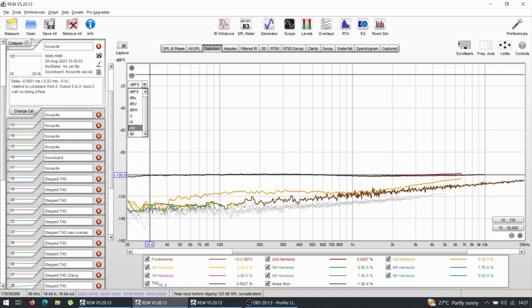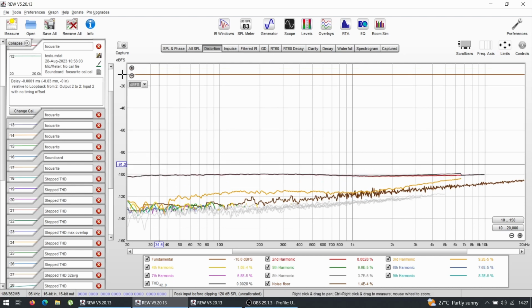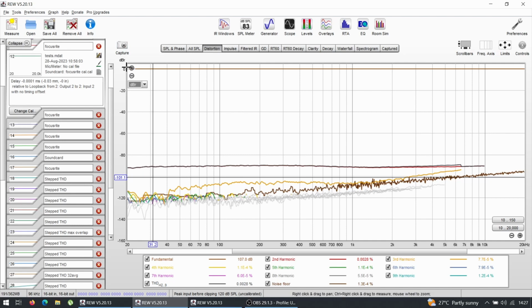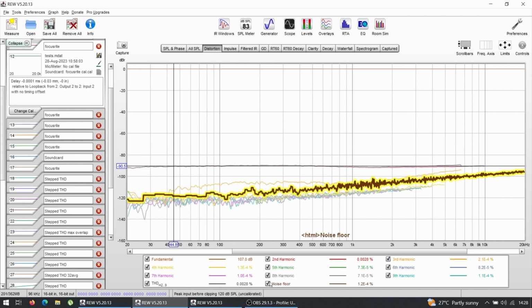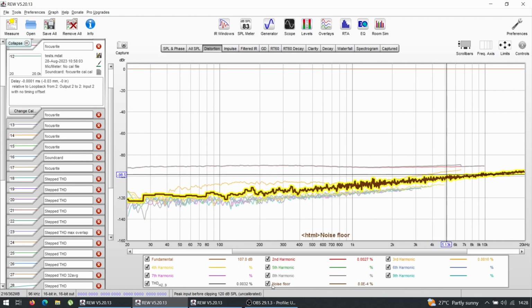We can do dB relative, so it's relative to the signal. Because on dBFS we have minus 10 signal, and this is about minus 100. But THD is not minus 100 because the signal is lower. So we choose a relative one, which puts the fundamental at 0 dB. And then we see that this audio interface has THD of 90 dB down. And the floor noise, for example, you can choose whichever you want to see. The floor noise is about 120 dB down, and it rises with frequency all the way up to here. And we can check the THD, the noise, and other stuff.